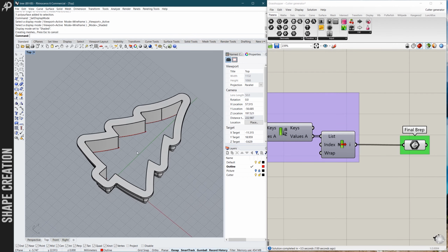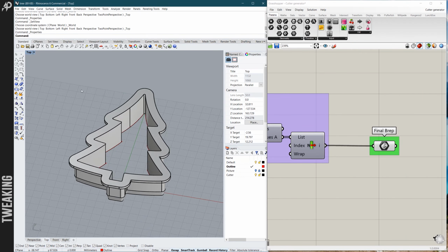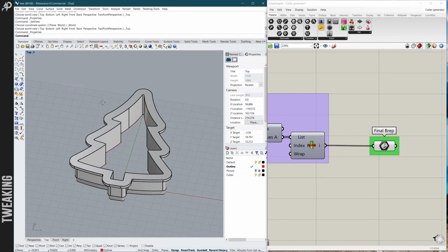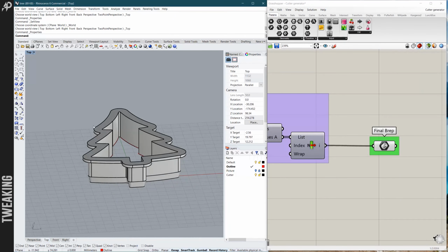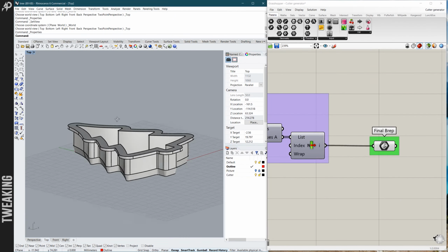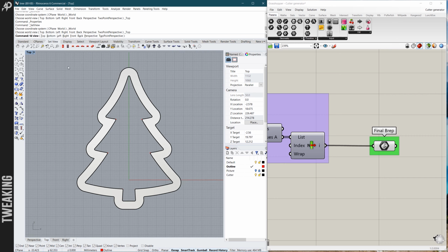Okay, so what is here to improve? First of all, in the last video sequence I've made one thing that you might be wondering how I did it. I was still in top view and I started rotating. You do this by holding Control, Shift and right mouse button at the same time. Then you release the orthographic view and you can then rotate from then on. If you wanted to restore the perpendicular view, you just go into set view, and here are self-explanatory icons of the view, so I just would return to top view.